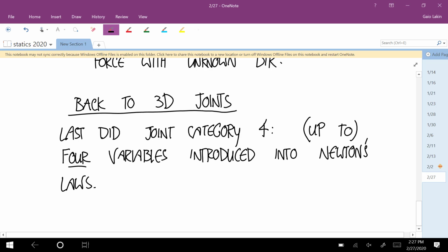And the way that works, so that was a pin joint without thrust. And this is an example of that. If you think of this as a single pin joint, this doesn't allow rotation this way. It doesn't allow twisting this way. It does allow this. That's sort of what it's designed for. And also, if you think of translations, it doesn't allow me to translate this forward and backward. It doesn't allow me to translate it up and down, but it does allow translation this way. So that's what it means by no thrust. Thrust is along the axis of the pin. And so this doesn't provide any force along the axis of the pin, okay?